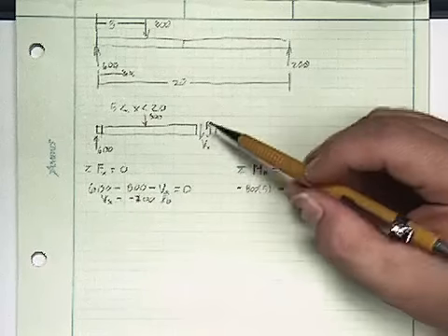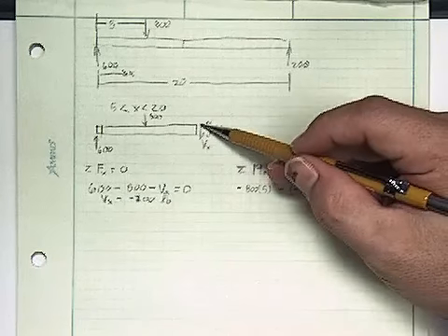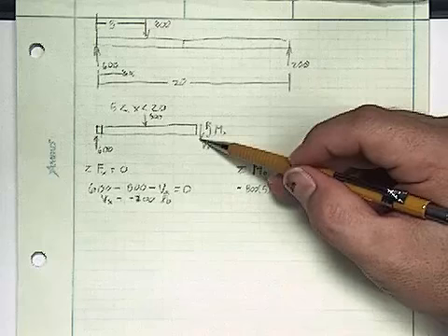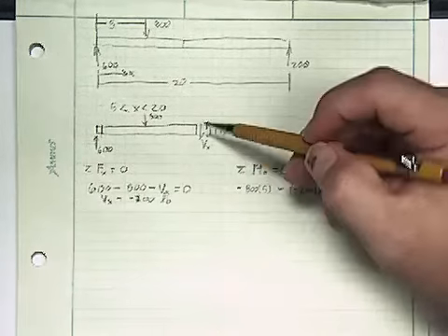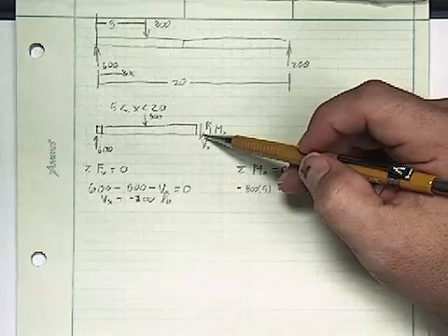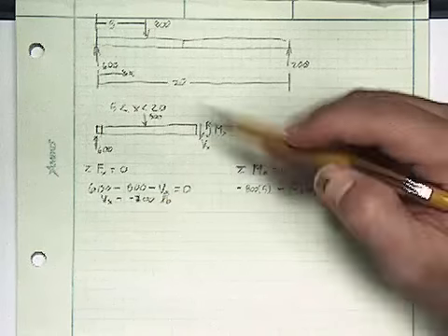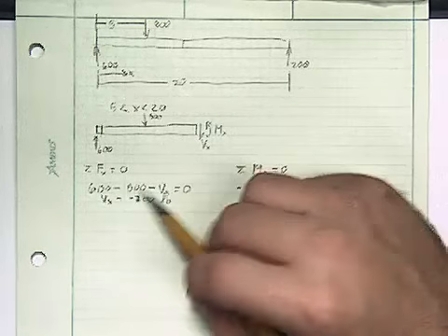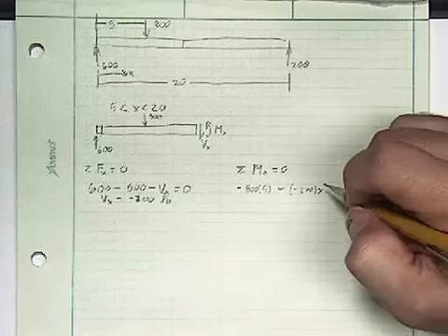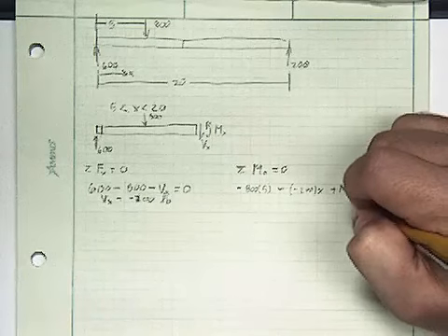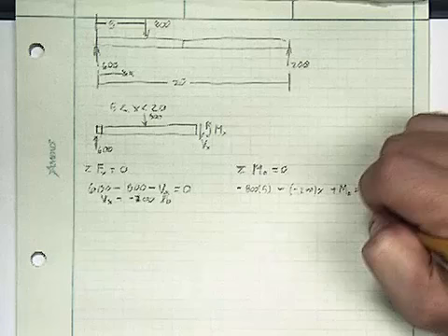So actually, I could have shown it by having it point the other way, but we'll have it point the positive direction from the understanding of how shear occurs. It is in the negative direction of the y-axis, so it's labeled, so when I sum my forces, it's negative. And I need to add the moment and set all that equal to 0.